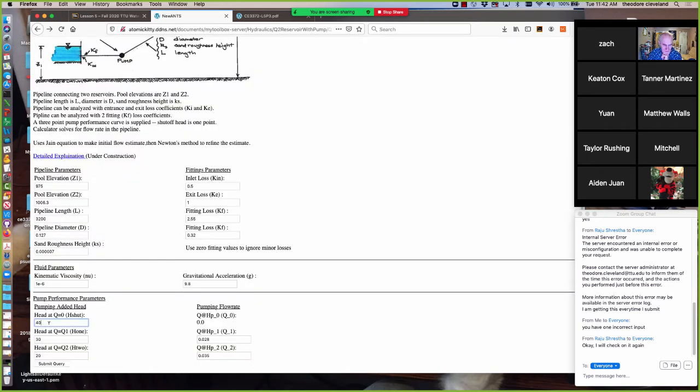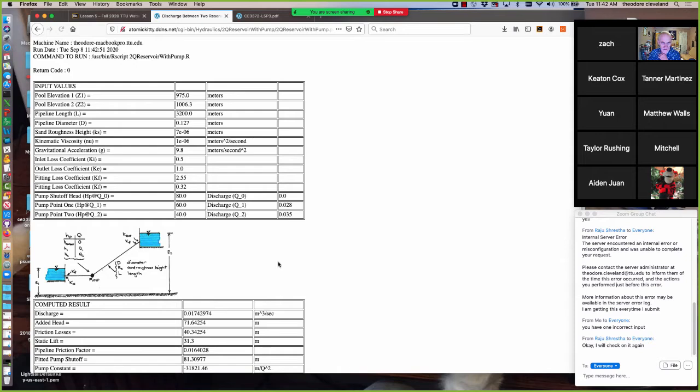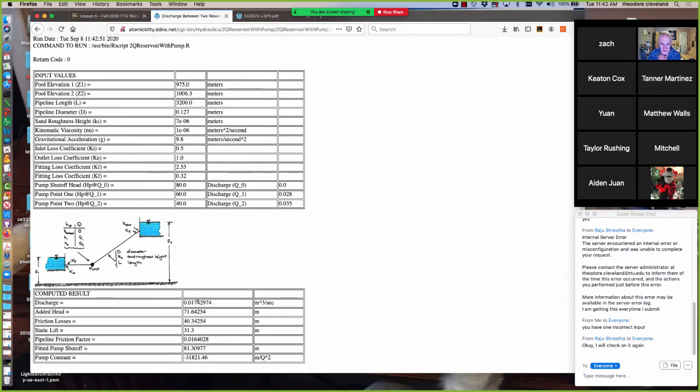So all the heads double if we put 2 in series. So we're going to put 2 pumps in series, so that 40 becomes an 80. That 30 becomes a 60. That 20 becomes a 40. Nothing else changes. So now we have 2 pumps pushing into each other, and we get 17 liters per second. Recall our goal is 24. So I would argue that this sort of works with 2 in series, because we're probably not going to need 17 liters a second very often.